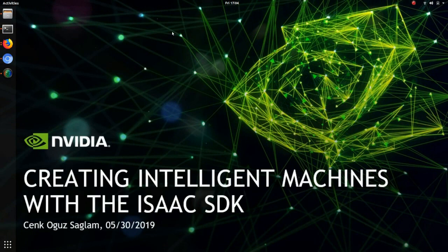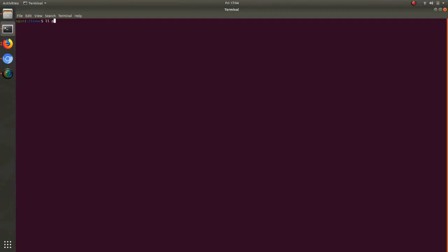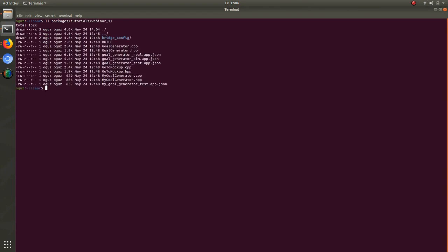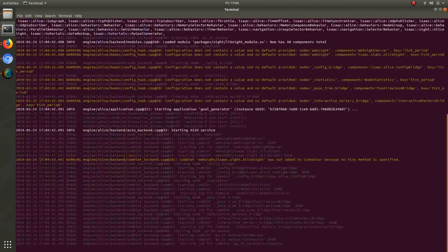To get started, download the nightly build from the Isaac website, untar it, and use the install dependencies script as instructed in the documentation. Once you do that, you'll find the folder we have created for this webinar under Packages, Tutorials, Webinar_1. To run your first application, just type bazel run Packages, Tutorials, Webinar_1, my goal generator test. To stop your application, simply hit Ctrl+C.